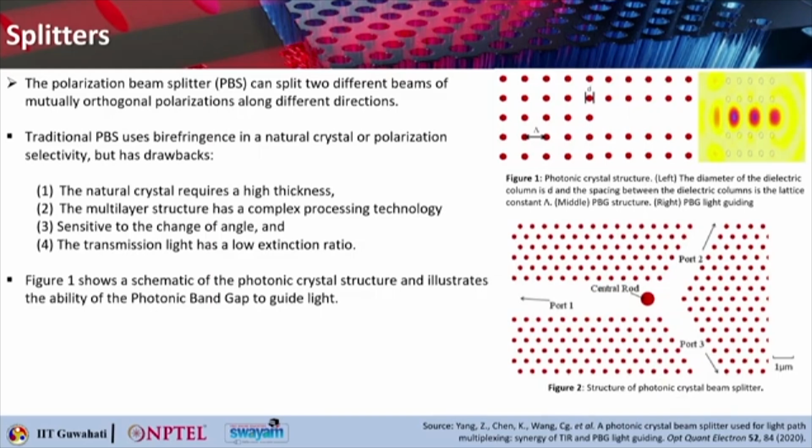In order to realize the light path multiplexing function, in addition to the necessary channels for splitting and cycling, the asymmetry of the photonic crystal microstructure must be considered. That is, an asymmetric microstructure must be designed in the photonic crystal beam splitter to satisfy the asymmetry of the input and the output light path.